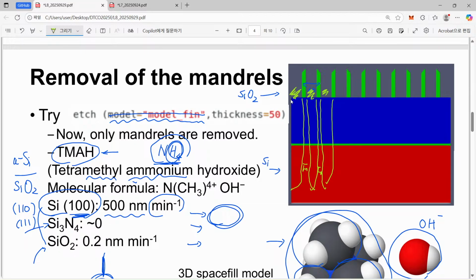So that's the reason why, instead of this silicon dioxide, here we have a hard mask. First of all, our pattern made in this silicon dioxide layer is transferred to this hard mask layer, and only after that, using this hard mask layer, is the silicon patterned. Why? I have a little idea about that, but according to the references, it is closely related to stability of materials.